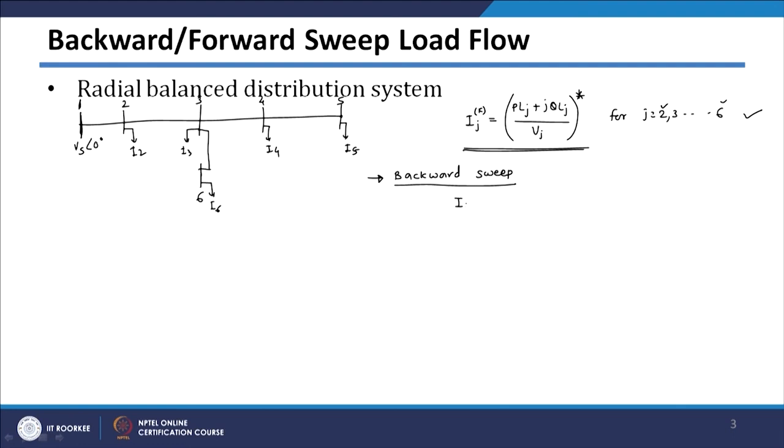Say I45 will be equal to I5. The current in this branch will be just the I5 current. Now the current I34 will be equal to the current between I45 plus I4. So it will be I45 plus I4, which is already calculated, and you can use it here. Then current I36 will be equal to I6, because in this branch only the I6 current will be flowing.